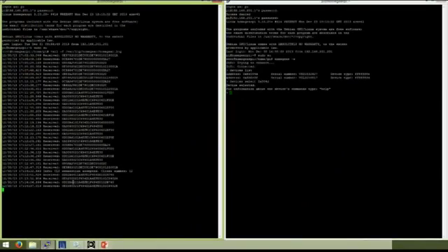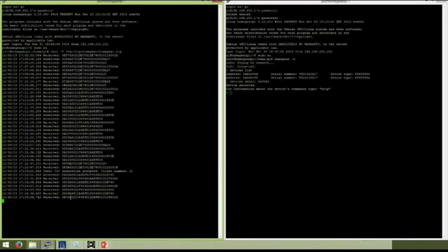But you can see already, here is the packet we just talked about with the message type 41. That is the sender address. You can see the sender address and the destination address being the address of the switch. Okay, there it is again. And there is the packet after that. Remove the battery. The packet after that is the acknowledged packet from the switch.